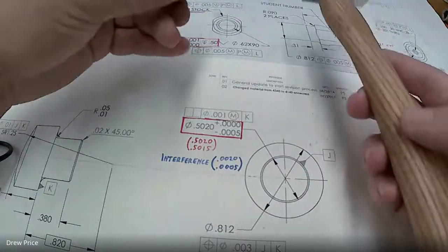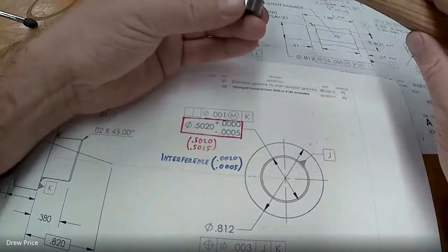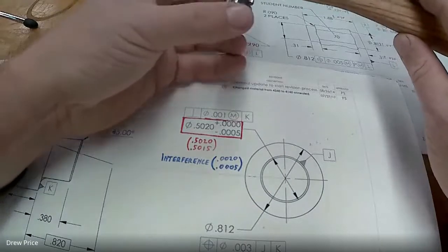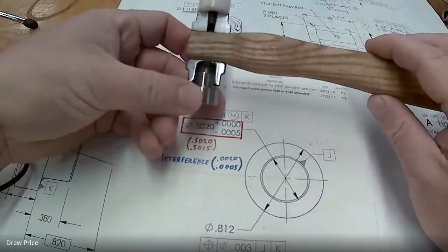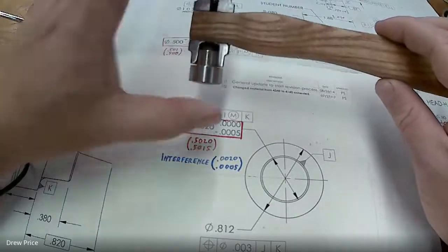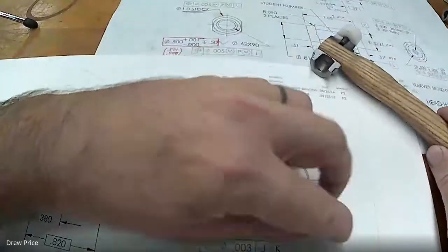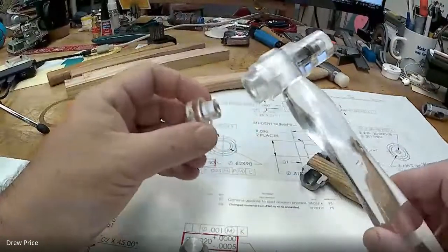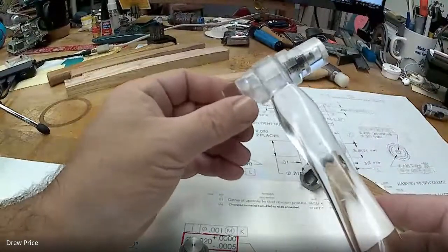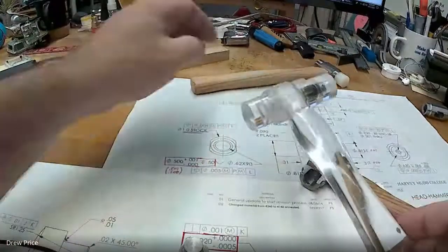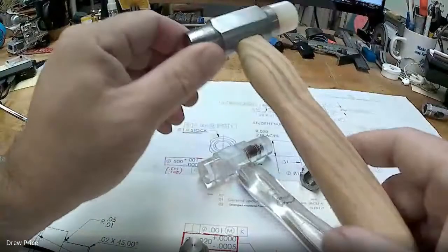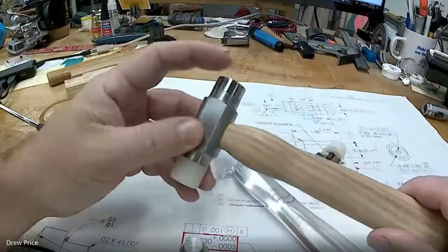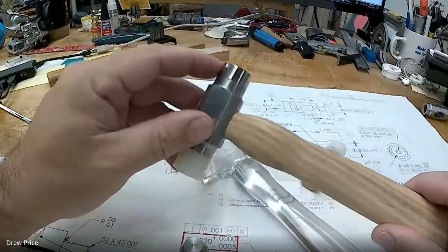And that's really important because for something like this demo piece, we changed the tolerances a little bit to make sure that they fit together snugly, but still allow me to remove them by hand for a demonstration. Same thing for this demonstration piece. I want to be able to remove this, but still have it be a tight enough fit that I don't lose one or the other. And in the finished one, specifying the fits like that allows you to permanently attach the two pieces to each other so that they don't ever come apart.